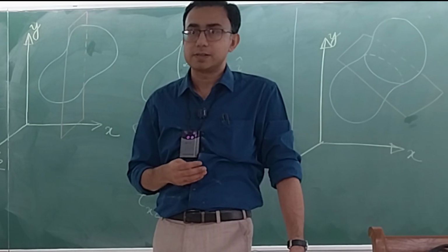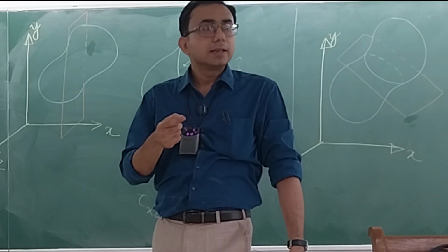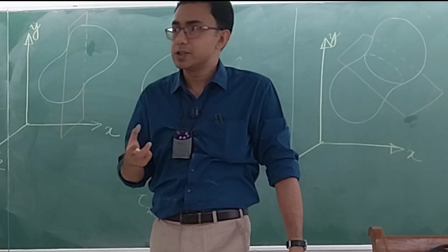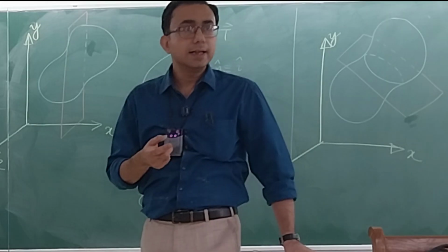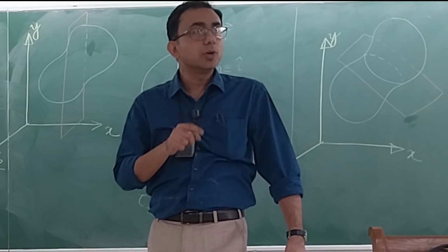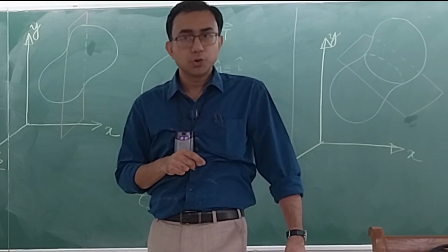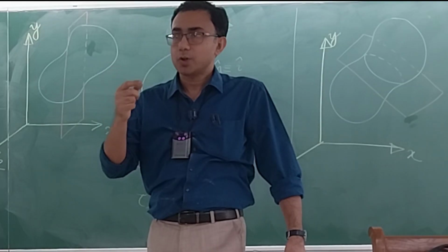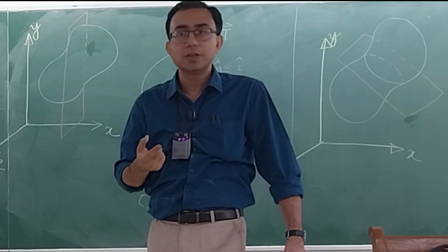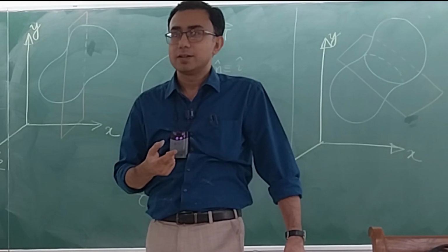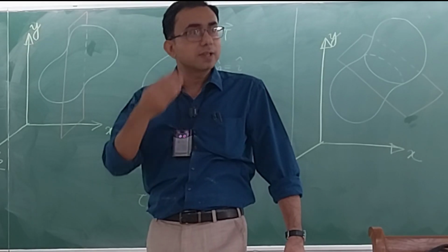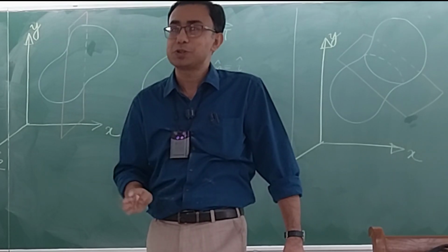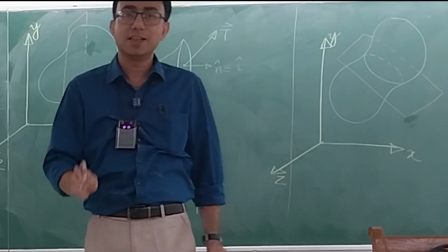Similarly, for shear stresses, when you consider the shear stresses which are generated in response to a torque-like situation, the torsion chapter, there you have tau is equal to TR by J. Do you not have that? Now, if you take different values of the radii on the same cross section, do you not have different values of the shear stress? So does it not make sense that on the same cross section you can have different values of the shear stress? It is absolutely possible. Not only is it possible, that is the general thing.